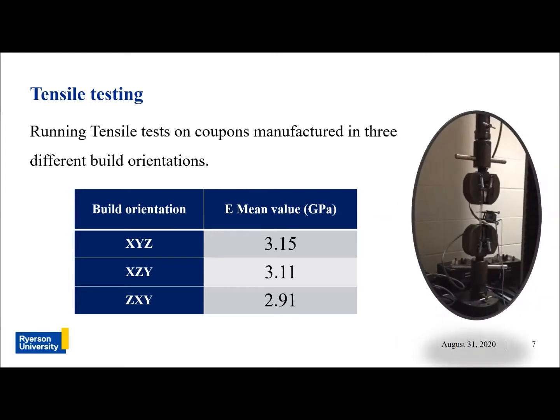These results from tensile testing were considered as reference, and they were used to define orthotropic PLA in the ANSYS database. The elastic moduli which will be obtained through the inverse identification method will be compared with the results shown in the table below.